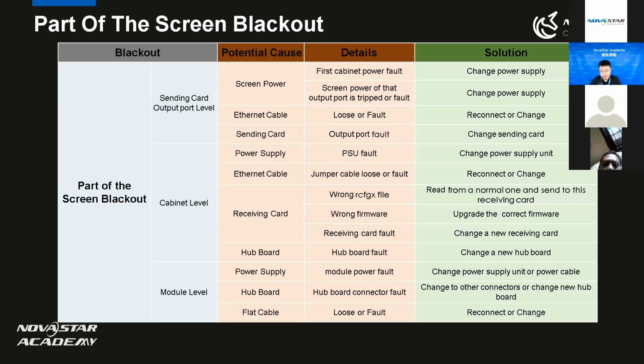And for the sending card, if the sending card output level is black, you may need to check if that output port is broken. So you can try to change a sending card, or use the other normal working output to see if the original one is broken.